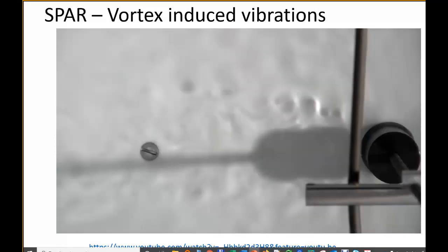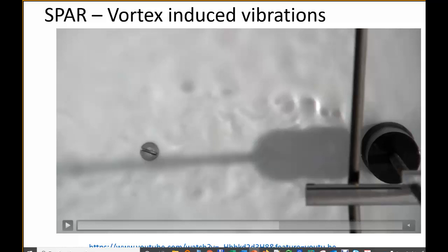When the fluid impacts the cylinder on this side, it won't create any problem if it could go all the way here and then continue on the flow. For example, the streamline will be knocking the right side, then following the contour and then leaving on this side. But it decouples, or it detaches early. So maybe we should make a small sketch.